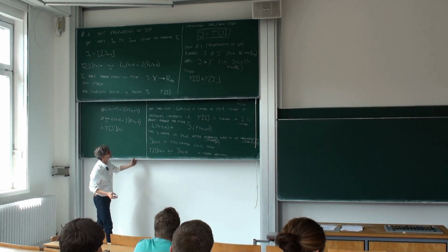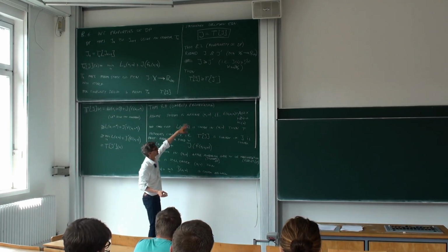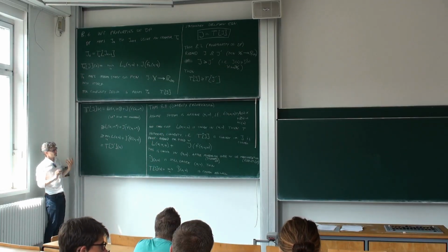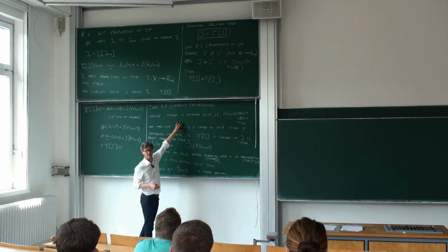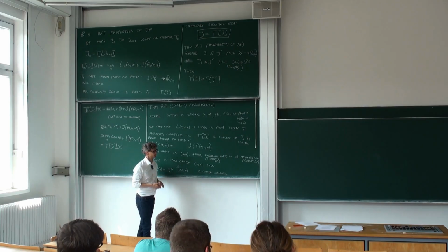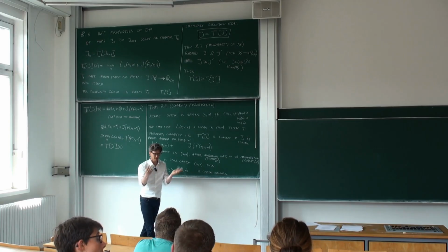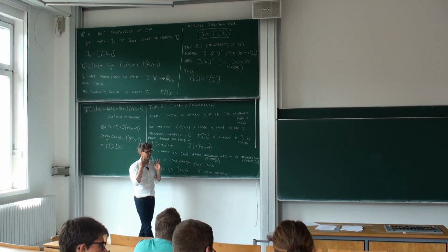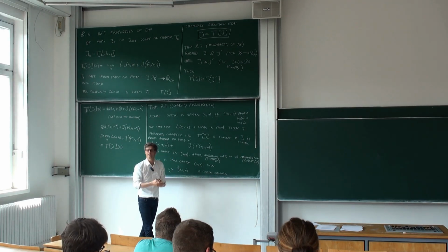But it leads to this remarkable thing that, independent of the dependence on w, for affine systems and convex stage costs, we basically get convex cost-to-go functions all the time. And that, for example, implies that if you have a linear system with a lot of inequality constraints, your set of feasible states will remain a convex set.